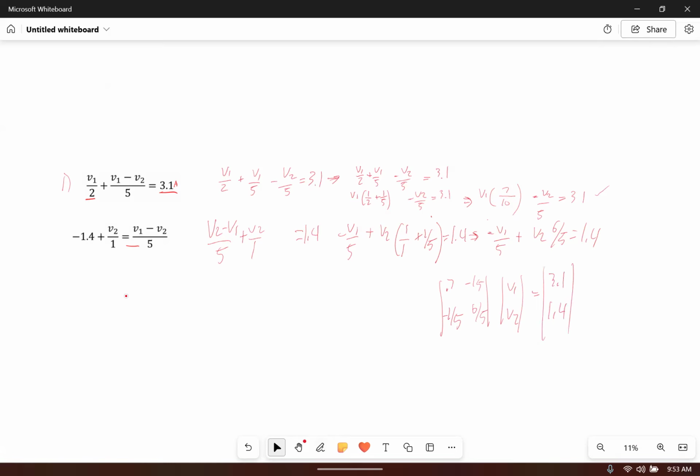Okay. So do you remember when I said I knew that there was something wrong because those two signs weren't the same polarity? When you're doing somewhat straightforward circuit analysis, the thing you can do to check your work is look at what's called the off diagonals. If the off diagonals have the same sign, and actually the exact same number, you're probably in pretty good shape. Because it didn't have the same sign, I realized that there must be a mistake there.